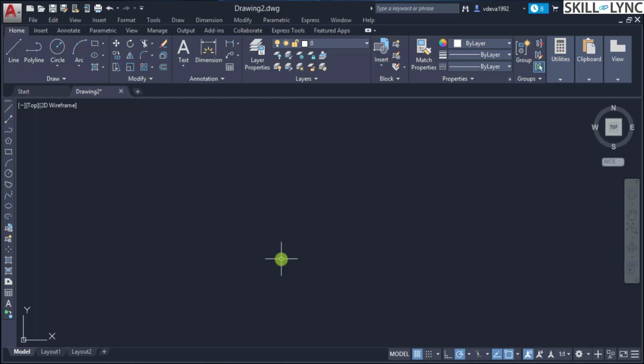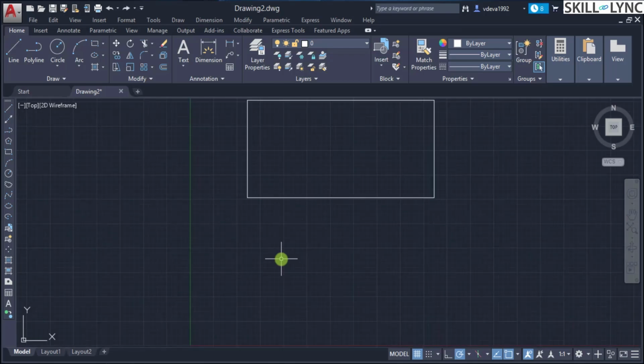So we roll back using the Ctrl Z option for the undo. Now let us repeat the same zoom command with the center option with a larger magnification height. Let us give the height as 500, so that means 500 mm is going to be the width. If you remember, the width of the page that we currently have is 594 mm, the limits.